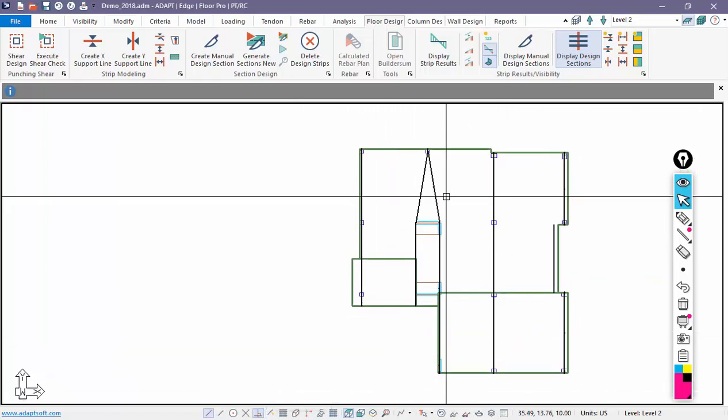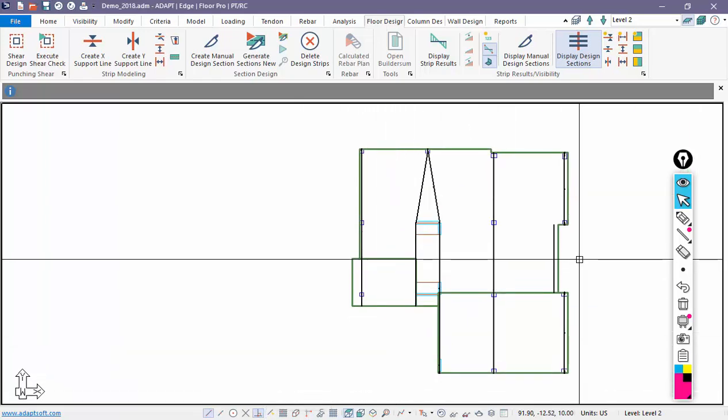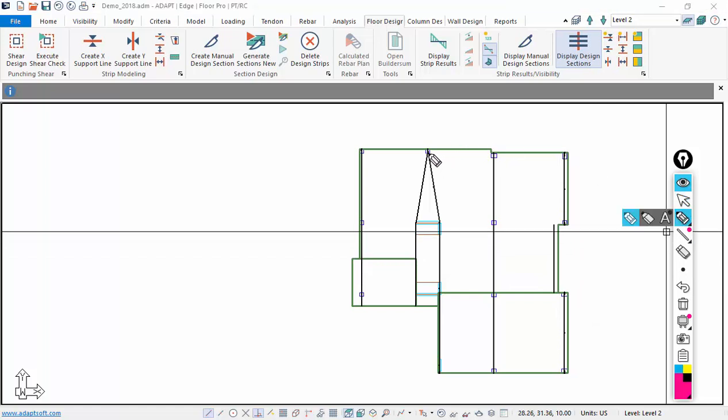So in this direction we have three locations where we need splitters. We have a point here that terminates from this support line. That's inside the slab, this point and this point. So we're going to add a splitter from this point over to this edge of slab, over to this support line, edge of slab, and along here. This cleanly identifies zones. Here's zone 1, here's zone 2, and zone 3 where the program can break the tributaries up.